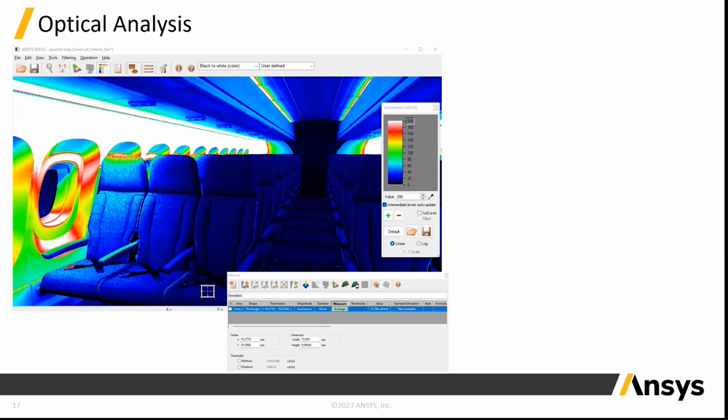So, and also optical analysis. Here we have a result opened in the virtual photometric lab, and it enables you to visualize spectral luminance maps. And then you can open the measures tab and set up different types of areas, define size, or enter the type of magnitude to measure, then see the flux or average or anything else.